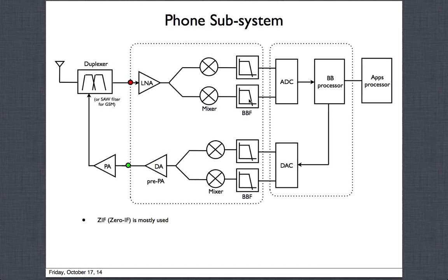We have some sort of filtering that goes on. I'm calling it a baseband filter. This could be single order or second or third, depending on how you design it, what you need, and how many jammers you have to filter. This will also have some gain tuning in it, which is called PGA or VGA. I'm not showing that, but some kind of gain programmability is also there.